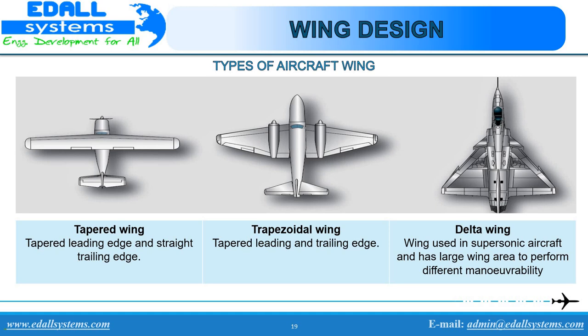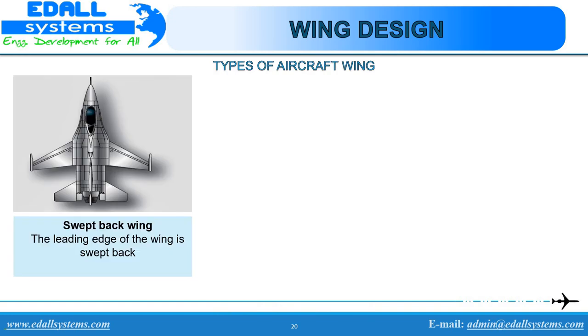Delta wing, triangular planform with sweep leading edge and straight trailing edge, offers the advantage of a swept wing with good structural efficiency and low frontal area. Disadvantages are the low wing loading and high wetted area needed to obtain aerodynamic stability. Swept back wing. This wing sweeps rearwards from the root to the tip. At transonic speed, swept wings have lower drag but can handle badly in and near stall and require high stiffness to avoid aeroelasticity at high speeds.